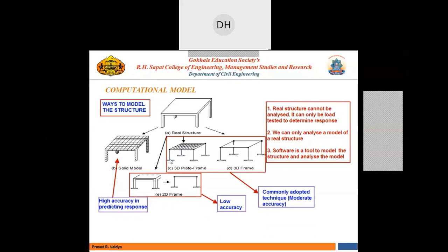Like that, we model one element where you have got two nodes, and each node will have 6 DOF at the end. So this is actually reduced to a line element, right? The solid element is reduced to a line element. And again, you can model a plate also at the top to represent your slab. So this is a 3D plate model.